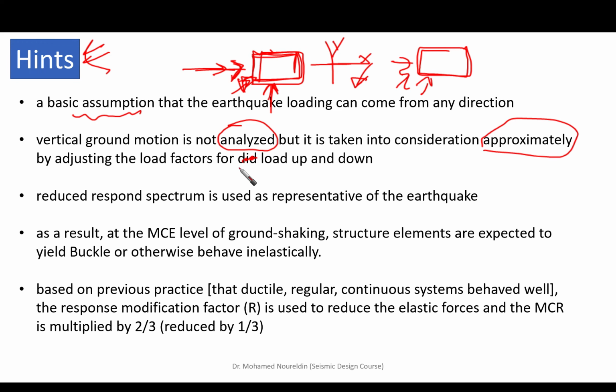The earthquake has a vertical component and a horizontal one. The vertical component is not considered in analysis, except for rare and special cases, for example when we are near a fault, or in seismic design category E and F, where we need to analyze the vertical component. But generally, we don't consider it in analysis.